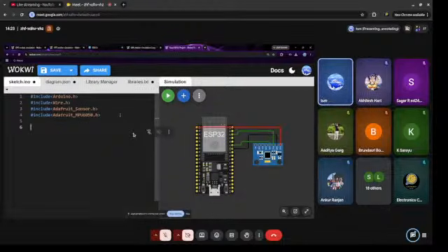For example, here we will talk from the ESP32 to the accelerometer. And what the Adafruit Sensor library does is provide a common sensor interface. I will show you the interface afterwards. And Adafruit MPU6050 gives us functions like MPU begin, MPU set accelerometer range, and get event. Okay, we will explain that now. Okay, we will start.